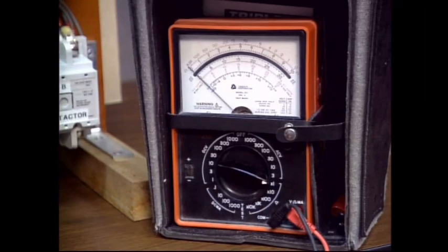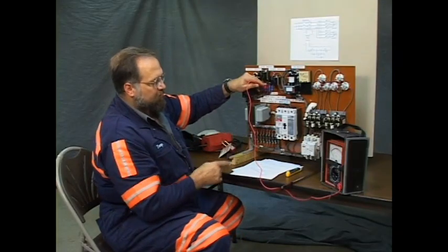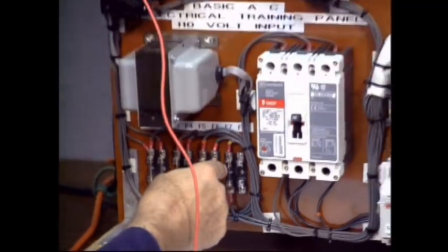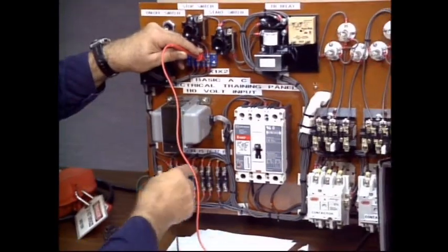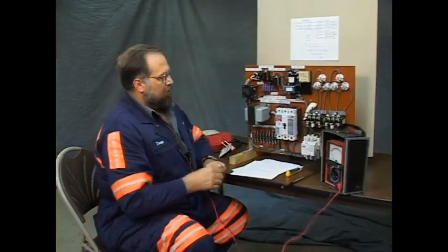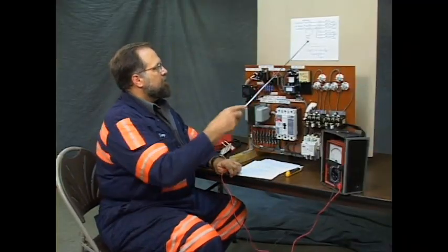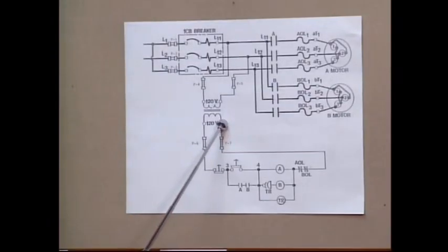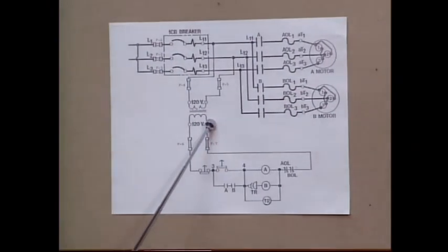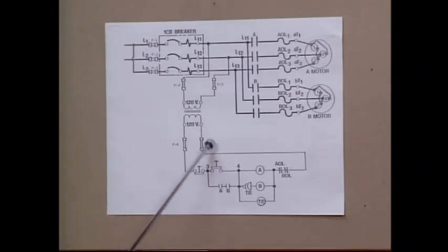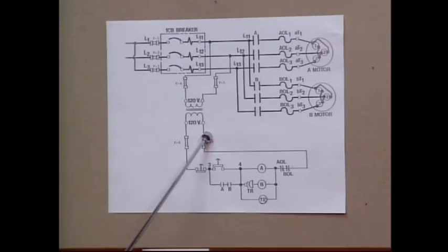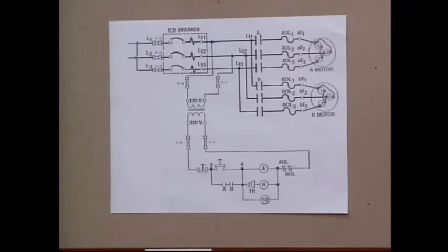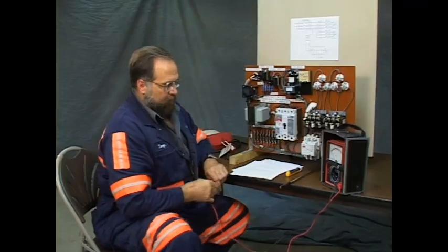Uh-oh. I don't have a circuit. The line side of F7 reads open. The problem indicated is from the X2 terminal, secondary of the control transformer, to the line side of the F7 fuse. The wire connecting the two is open.